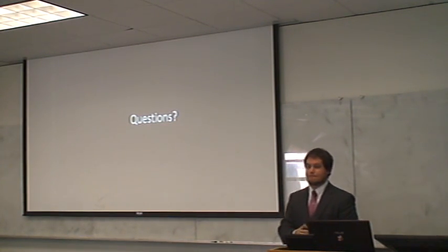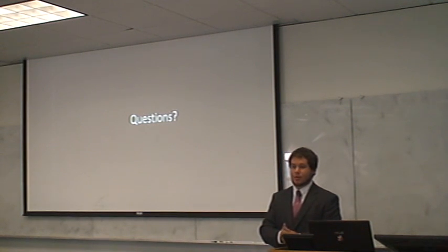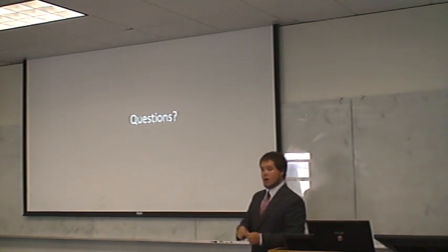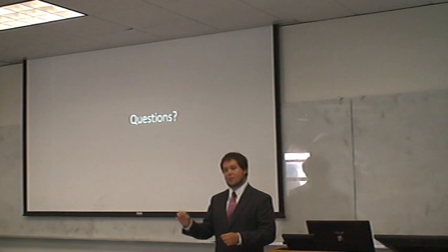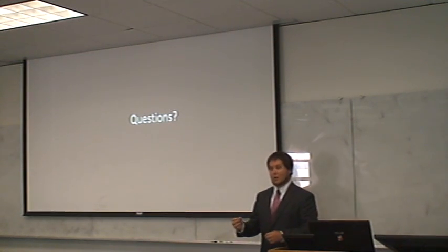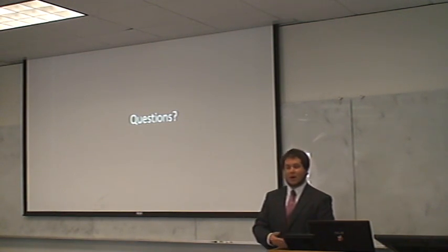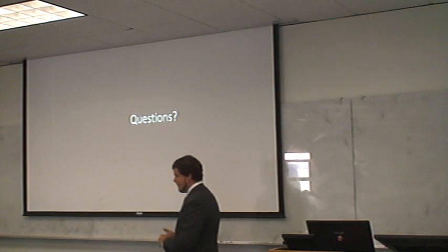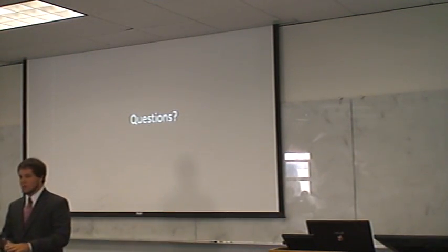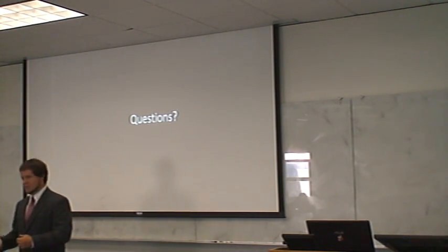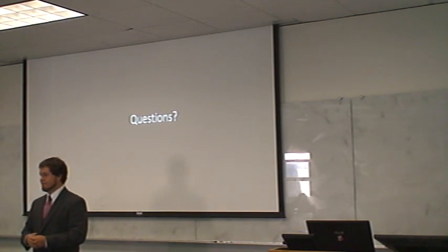Yes. How do you calibrate these sensors? How do you know the sensors are telling you the truth? That's what I was talking about, the environmental chamber. We can run the sensors through a temperature ramp and a humidity ramp, and we can get those calibrated. We can also measure soil moisture by volume and get a rough estimate. Again, the soil moisture sensor and the leaf wetness sensors are both relative. They're not meant to say you've got 33% moisture by weight or by volume. They're just saying it's dry, we haven't been watered in 3 days, rather than a specific amount.